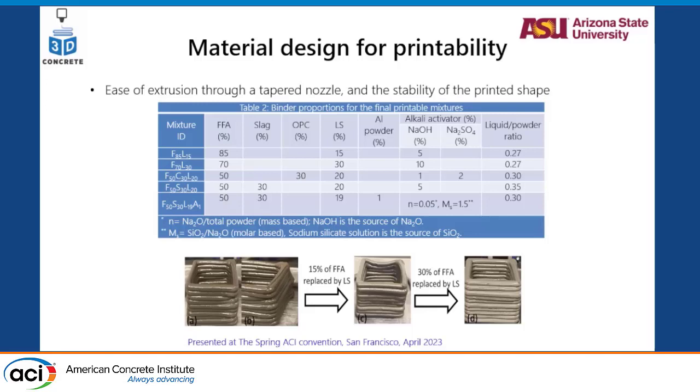Liquid to powder ratios, and so we used some limestone powder. Also, again, limestone, in all our work, we have come to love the use of limestone powder, even to 15, 20, 30%, because limestone powder with controlled particle sizes gives such a range of flexibility to use a lot of other materials. Not just that limestone does or does not do. We can have that debate in a completely different committee, but from a printability point of view, limestone does add a lot of flexibility to what you want to print.